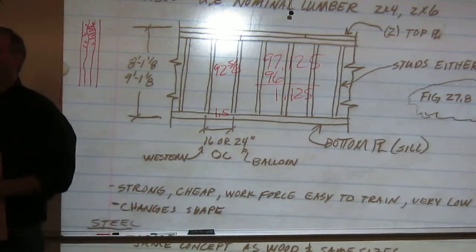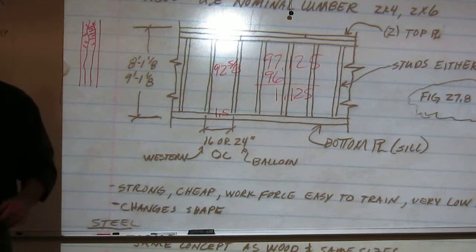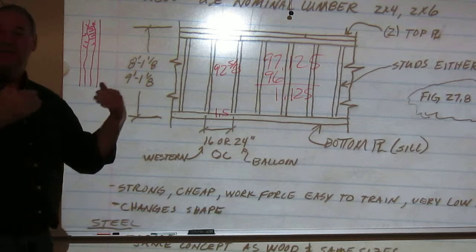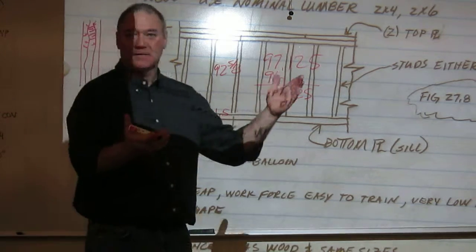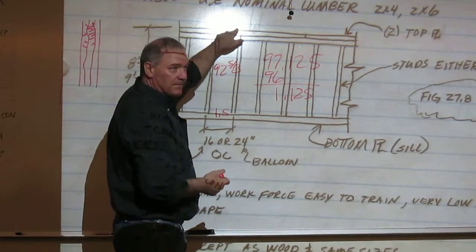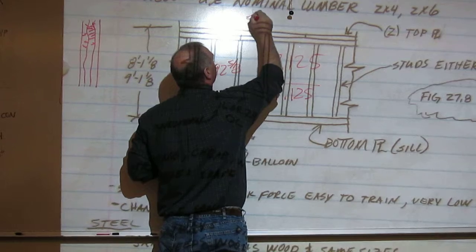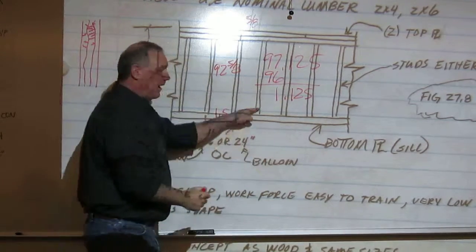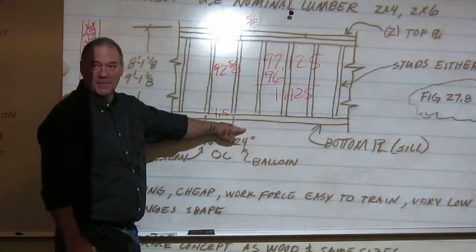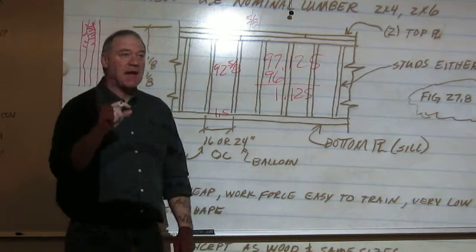Why would we build this wall at this weird configuration? Well, it is to accommodate our interior space. We want an 8-foot clear. Typically on a ceiling, I use 5/8 sheetrock. So up here, I've got 5/8 sheetrock. On the bottom, we have carpet, wood, tile. Most of those floorings are around a 1/2 inch.